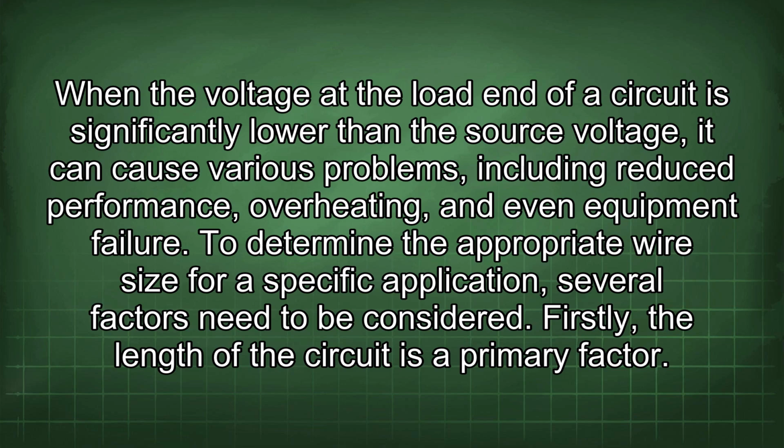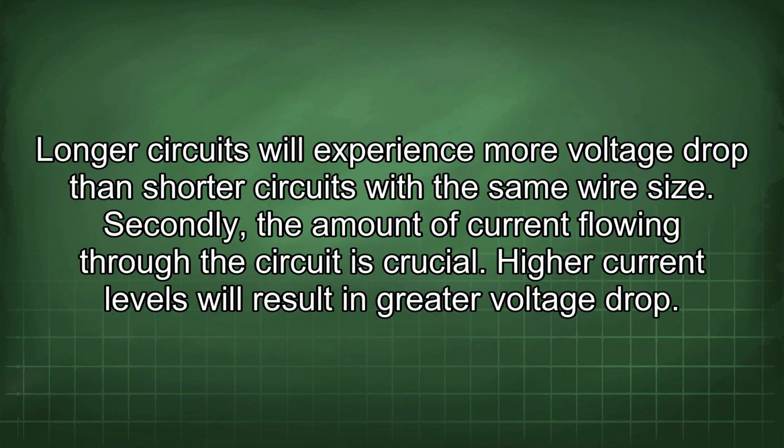Firstly, the length of the circuit is a primary factor. Longer circuits will experience more voltage drop than shorter circuits with the same wire size. Secondly, the amount of current flowing through the circuit is crucial. Higher current levels will result in greater voltage drop.